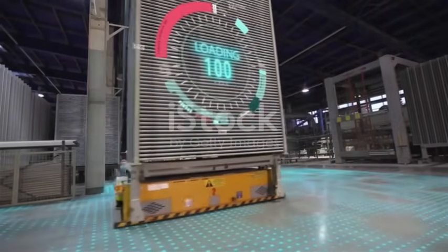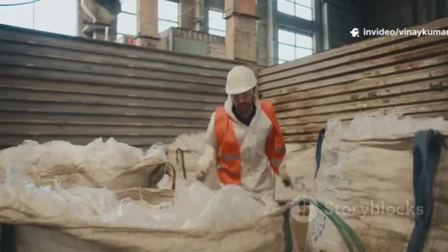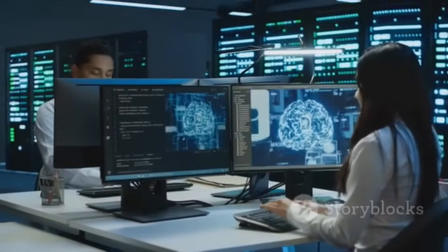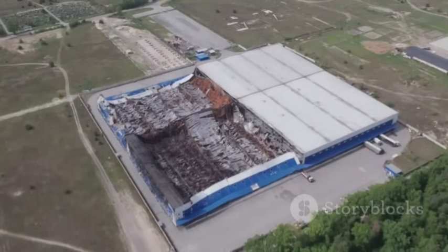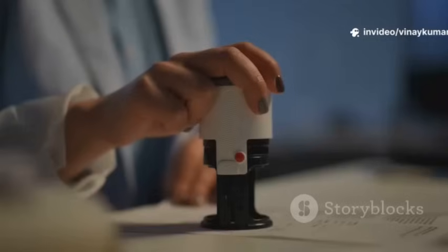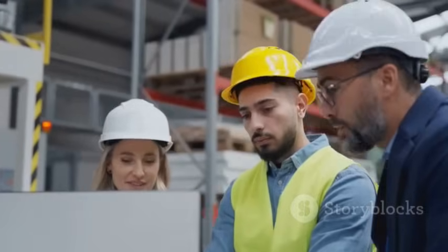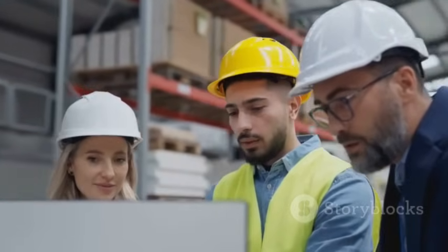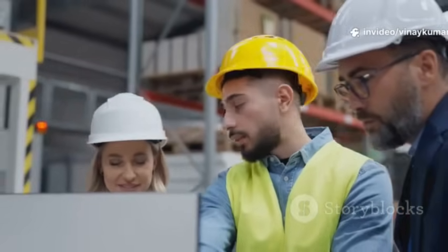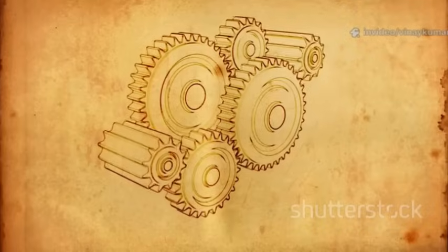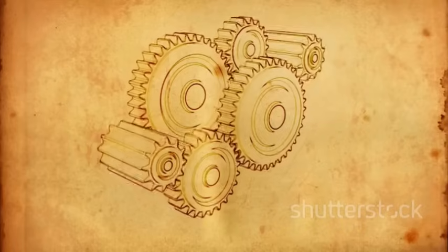Industrial processes are not static. They are constantly evolving. New technology becomes available, a different raw material is sourced, or maybe an operating procedure is updated. While change is often necessary for improvement, uncontrolled change is actually one of the most common root causes of major accidents. This is where our seventh element, management of change, or MOC, comes in. MOC is a formal process for reviewing and authorizing any proposed change to a PSM-covered process to make sure that the safety implications are fully understood and addressed before the change is implemented. It prevents a seemingly small, innocent change from having unforeseen and, honestly, catastrophic consequences.